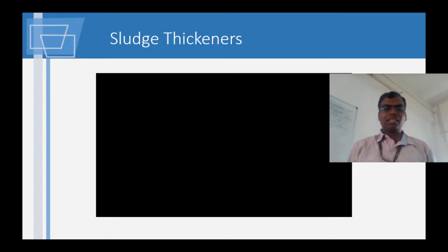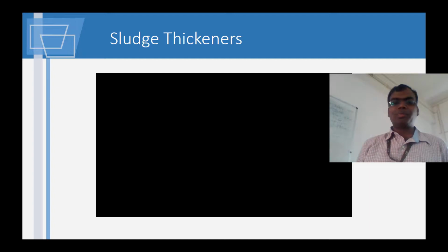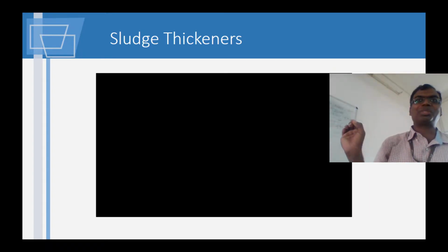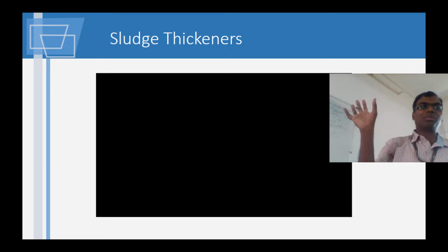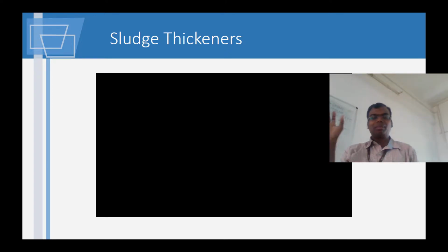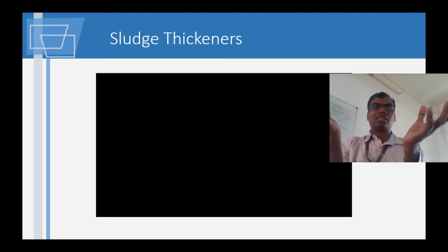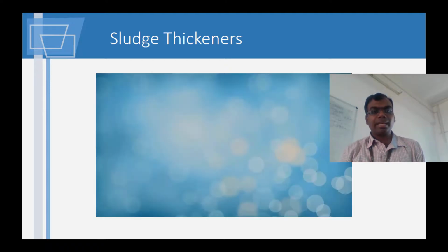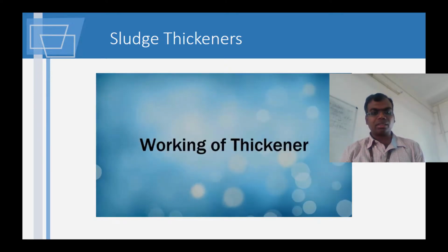Okay, basically if you have a look at this video, unfortunately I don't have a method to scroll the video and show. You saw a huge tank that looked much like your trickling filter. So here you have a small basin in the top. Everywhere the feed is from the center, where it will slow down the rate. It will come from the side, enter the tank.